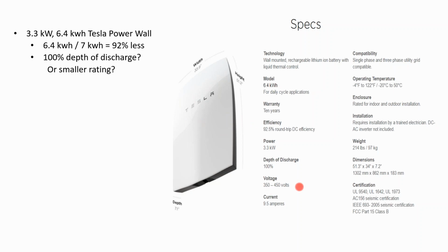We see our voltage being between 350 and 450 volts. And then we get to the current output, and it's only 10 amps. And you look at the breakers in your wall, and your electric service panel is full of 20 amp breakers. And they're not always using 20 amps. Usually they might be using 8 or 9 amps or 5 amps or less.